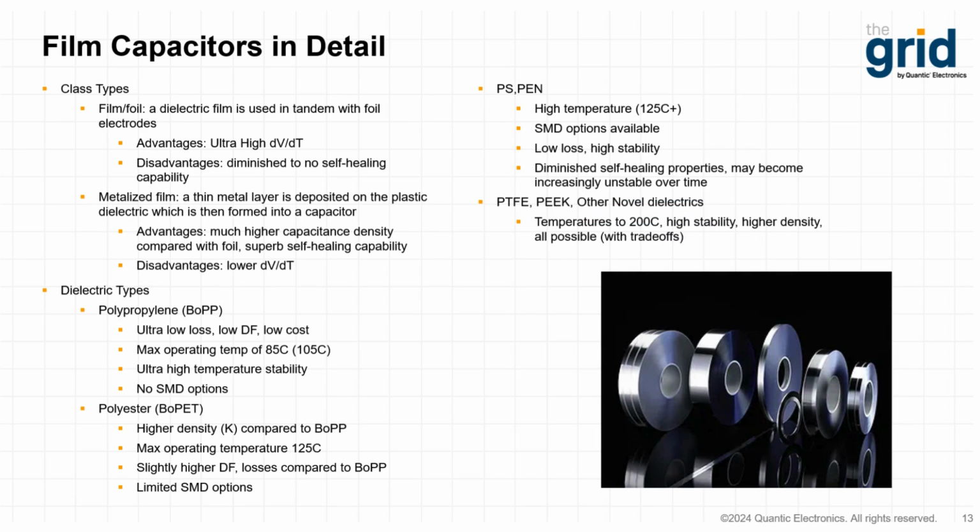Plastic film capacitors comprise the rest of the commercially available electrostatic capacitor selection, along with ceramics. Despite the overlap in the applications in the circuit, the two capacitor types, ceramic and plastic, couldn't be more different. While ceramic is rigid, plastic capacitors, even in constructed form, remain somewhat flexible. This property, along with the low crystallization of that dielectric material, makes plastic capacitors very capable at pulse and high ripple current applications, where ceramics can suffer fatigue from piezo effect and from thermal cycling stresses.